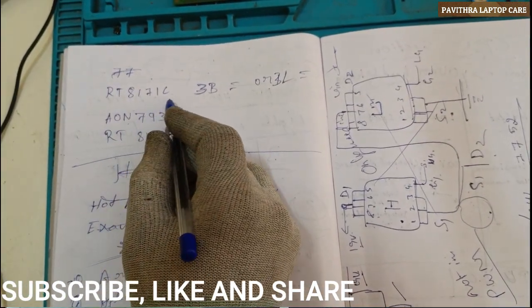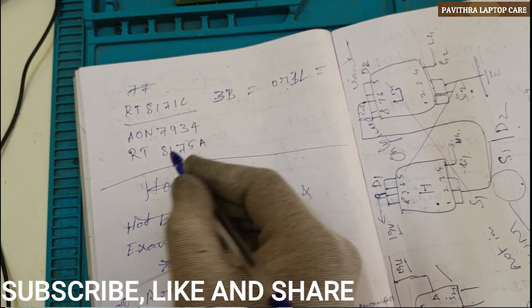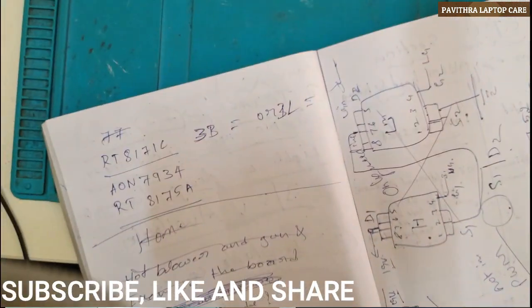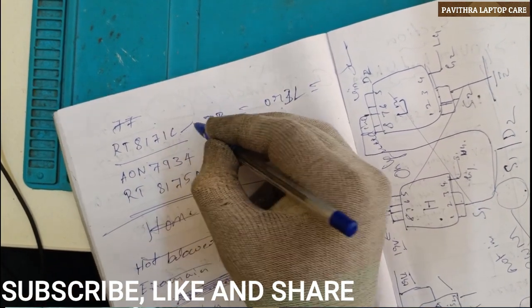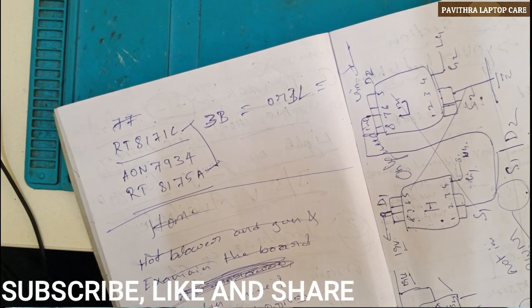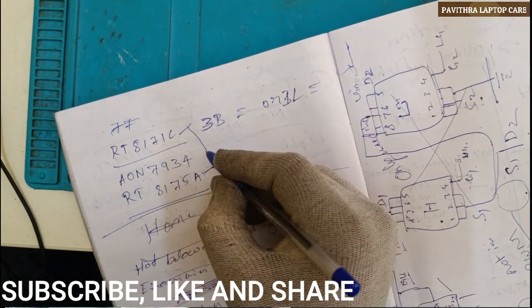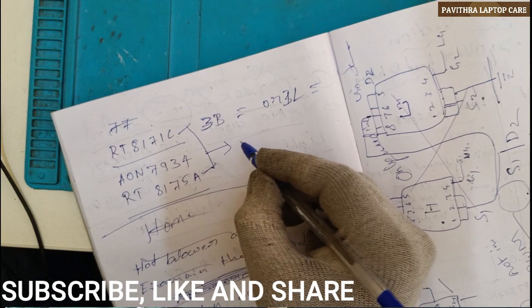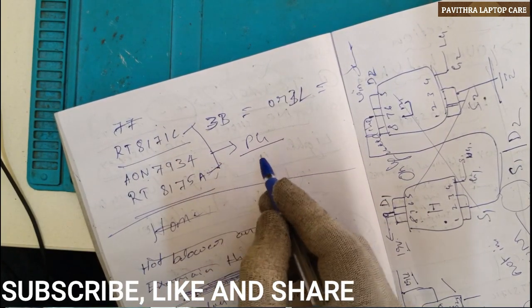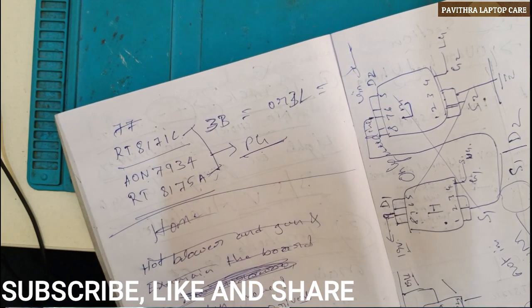This RT8171C and RT8175. Okay, these two ICs are the same in pin section, but one most important thing is the power good. Both ICs have different power good, okay?